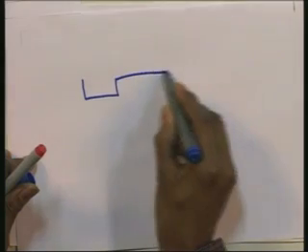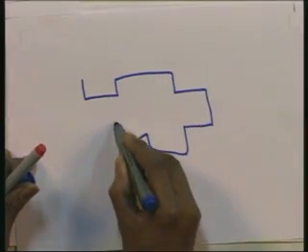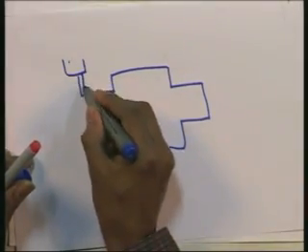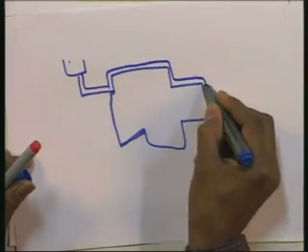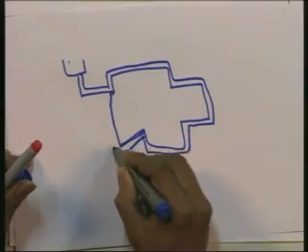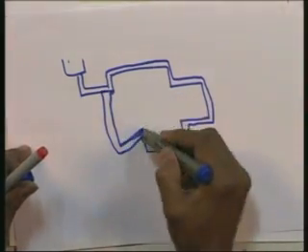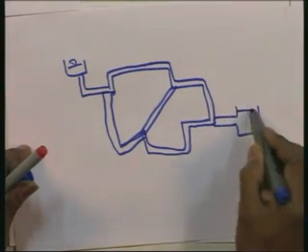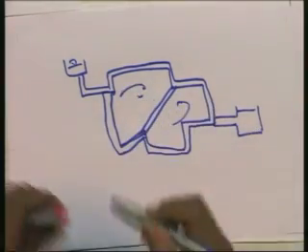Depending upon the problem, for example, most of the water supply systems which we provide to cities will have a network of piping systems going like this. Depending upon the problem, it may come and join with the same system, so it will be coming back to the system. This is called a networking of piping. If this is the reservoir, and here you have another reservoir or another location, there will be a loop here, one loop, another loop. So, this is a pipe network system. Depending upon the problem with multiple piping systems, we may have series pipes, looping pipes, branching pipes, or pipe networks.